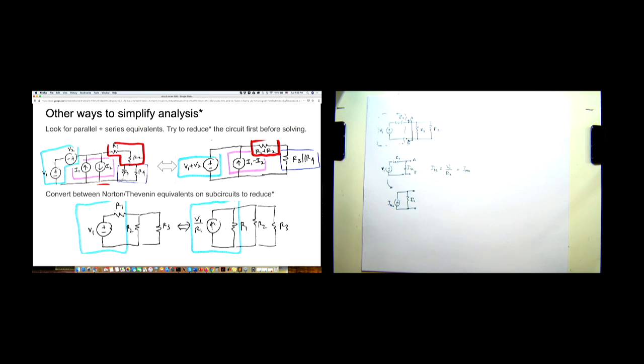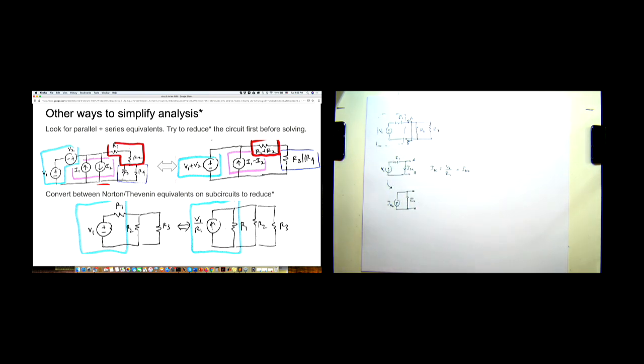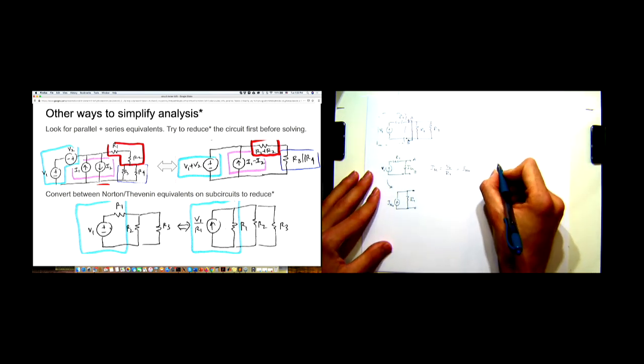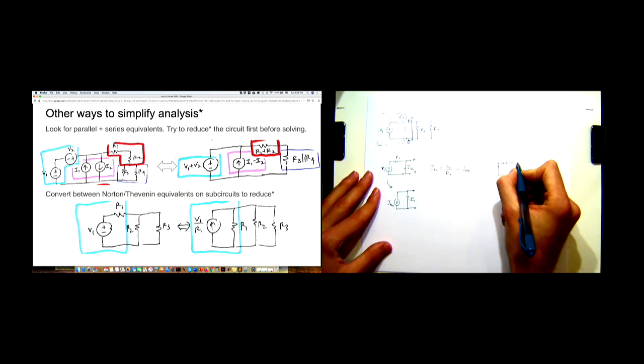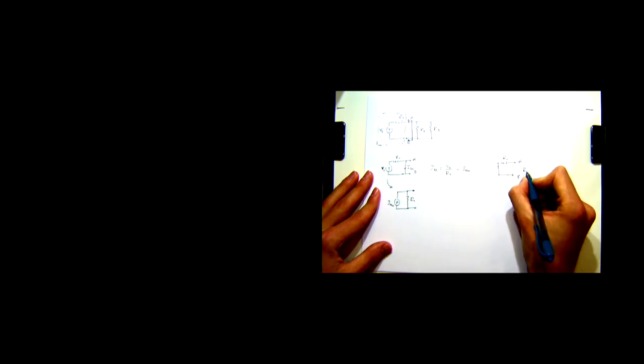And the equivalent Thevenin resistance, which is equal to the Norton resistance, is just equal to R1, because you just short circuit the current source. Does that make sense to everyone? Okay. I assume yes. So let's go into equivalence, actually, and repeat this point once more.